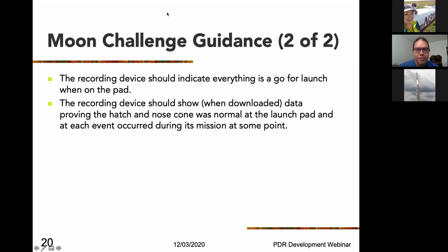Yeah, the hatch should open right at apogee and after apogee. Having a hatch open up during ascent under velocity may hamper the stability of the rocket. Okay. In addition, just making sure that the hatch opening is an option for an anomaly, that they have the ability to do any anomaly.